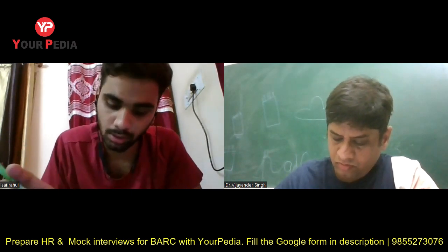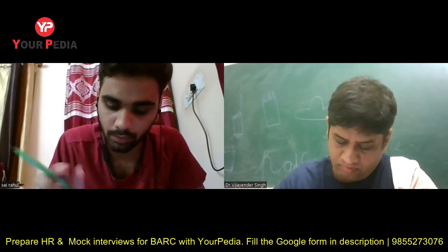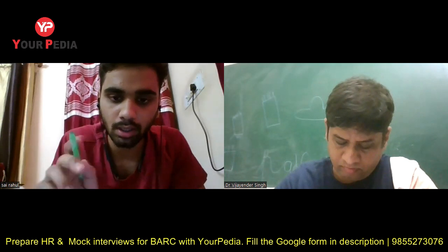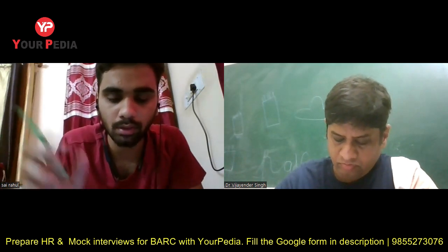Sir, unavailable energy will be T naught into dS, where dS is the change in entropy for both system and surrounding. For surrounding, it will be minus Q by T infinity, and for system, it will be MC ln T infinity by T. When we multiply it by T surrounding, the temperature of the surrounding, we will get unavailable energy.